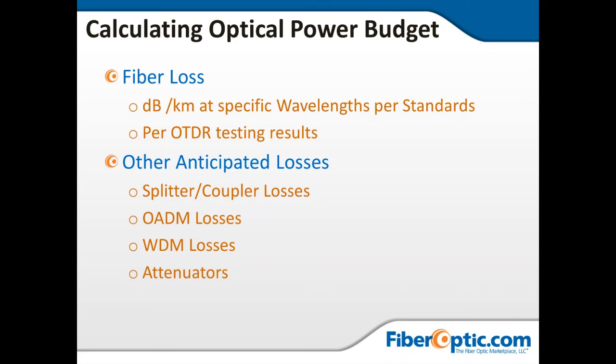If you pull the cable and wherever you got your cable from, it's out of spec, say 0.2 dB per kilometer, that's what you paid for. If it's higher than that, then it should go back to the manufacturer. It's not within specifications. If you've already installed it, you're very likely to be forced to live with it, and you really don't want to be in that position.